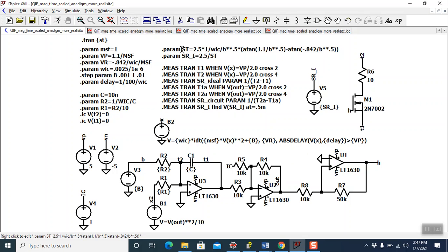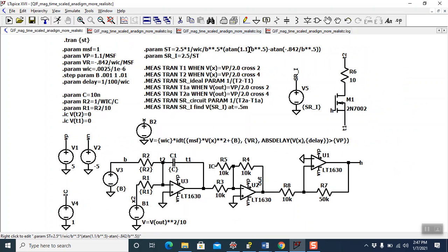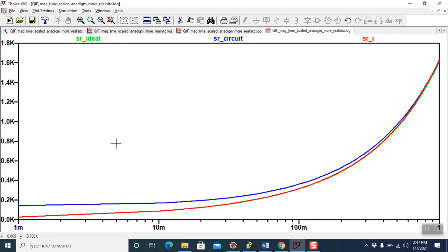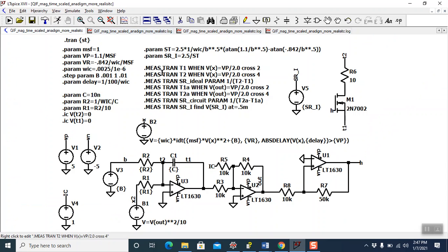All right. And here, just to re-point it out, is the spiking. The simulation time is just 2.5 times the period it takes to spike. So even though there's errors in this spike rate, I can use it to limit how long this simulation has to go. So each B, as it increases, the spike rate increases, and therefore I don't have to simulate for as long.